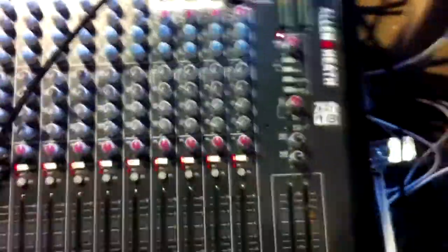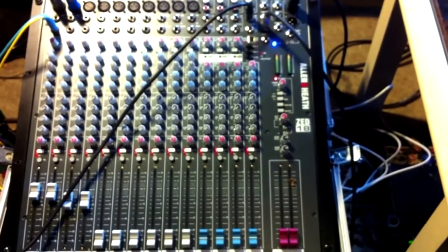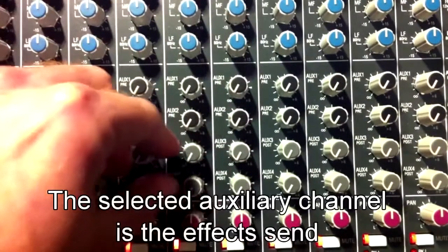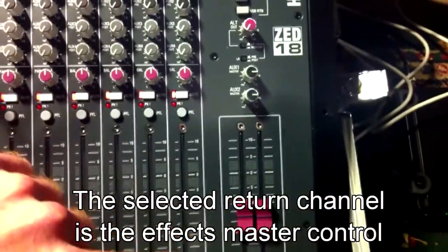So we could just use the monaural setting on the stereo 4 channel. And for each individual channel, we would control the effects level by controlling our auxiliary 3 send. And our stereo 4 channel would be controlling how much of that effects loop comes through to the main mix.